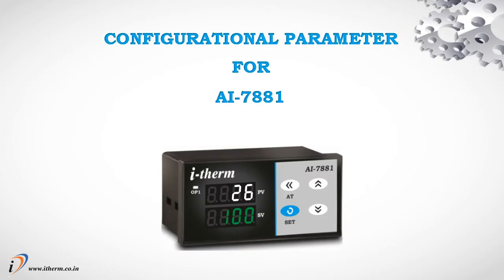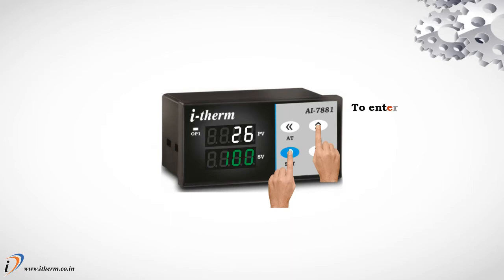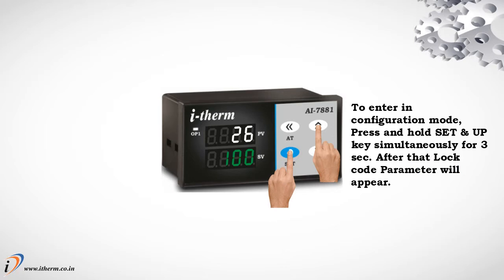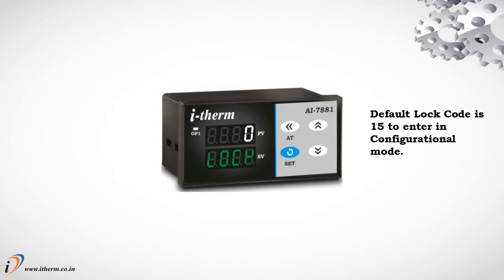Configurational parameters for AI7881. To enter configuration mode, press and hold the Set and Up keys simultaneously for 3 seconds. After that, the lock code will appear. The default lock code is 15 to enter configurational mode.